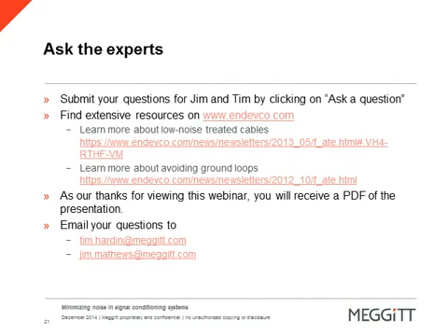Does the off-the-shelf accelerometer come with low-noise treated cables? Go ahead, Jim. Well, I can only speak to our product line. We have a standard low-noise treated cable with our single-ended charge-type devices that are specified in picocoulombs per G, if you will. Our IEPE or Isotron units do not have low-noise treated cable supplied with them, but all of our charge-type units come with a low-noise treated cable, typically our 3090C line of cable.